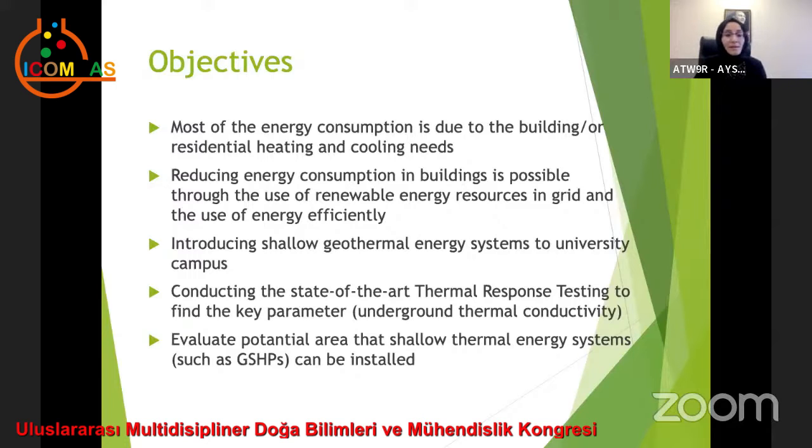I'd like to introduce the system to Balikesir. To do this, I start with state-of-the-art thermal response testing, because ground thermal conductivity is the key parameter to design a shallow geothermal energy system. We need to find reliable thermal conductivity values, and the best way is to run a thermal response test. Based on the test results, we can evaluate the potential areas where shallow geothermal energy systems can be installed in the Balikesir campus or other areas.